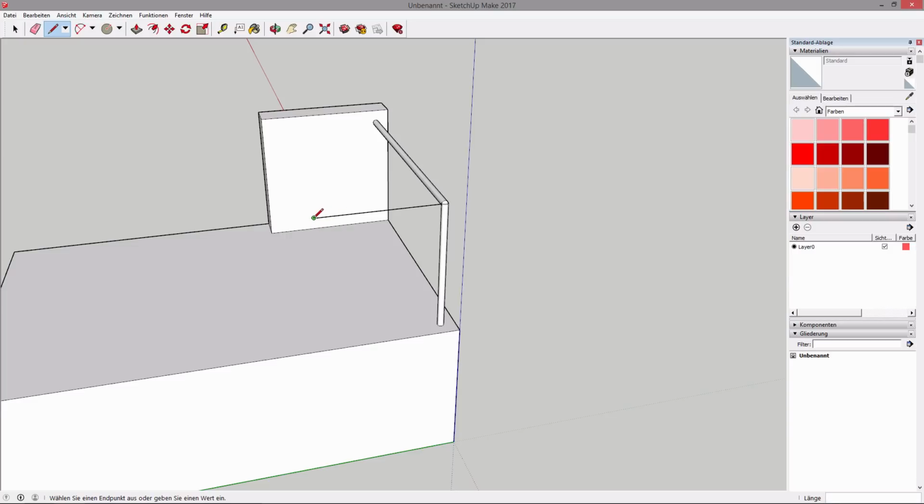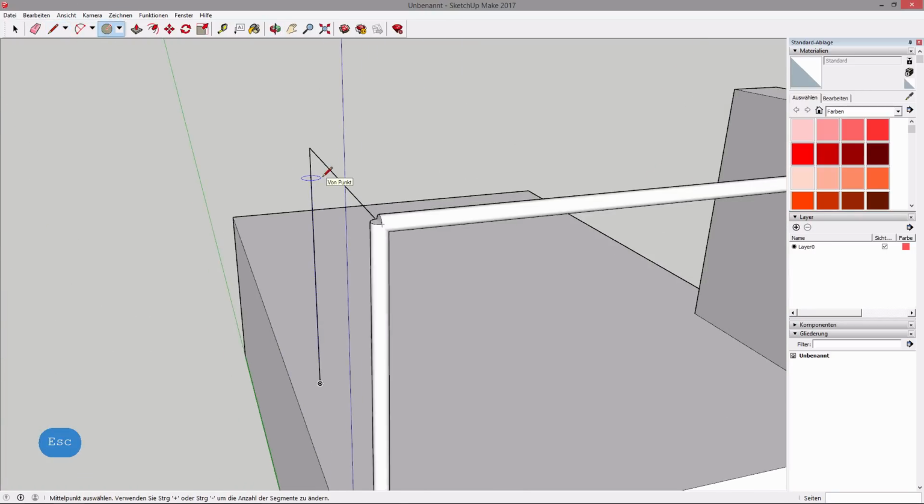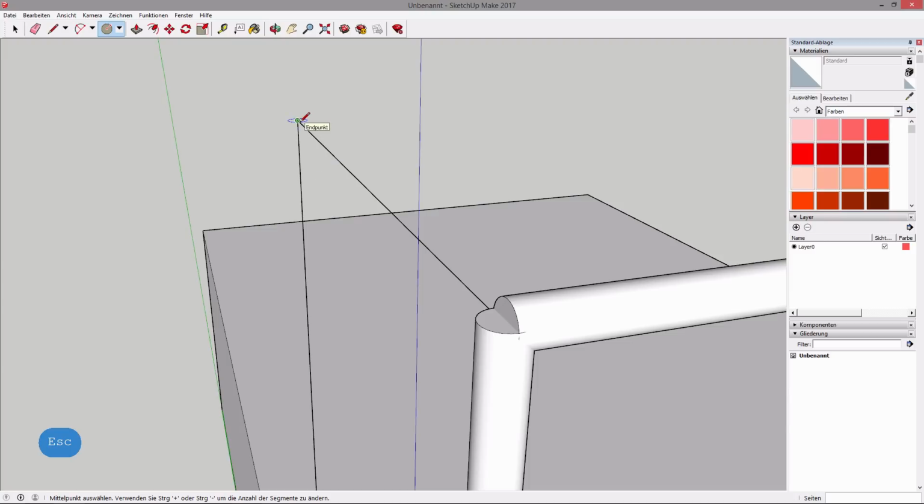click the endpoint, click the up arrow, and point somewhere on the surface we want it to be. So you can see if we point somewhere, it will be perfectly aligned to where we click. So now this is what we want. And now you can hit the left arrow, so if the circle is green, it's perfectly aligned again to the green axis.